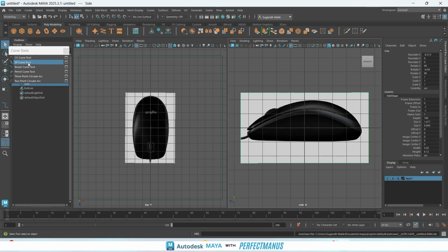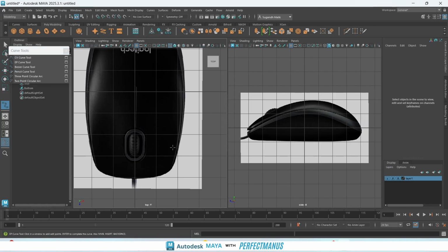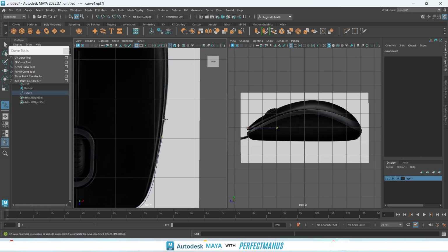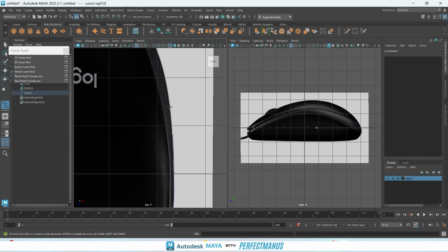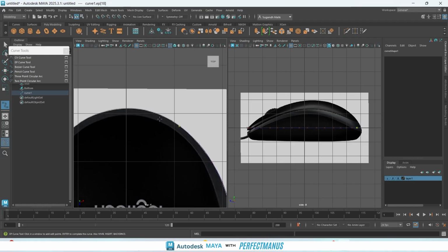We are choosing an EP curve and from the starting, okay, from this area you can start molding, or from this area you can start molding. So I will focus more on the top view because I need to follow these curves and I need those many points. Instead of creating them later on, we'll be focusing on creating those right now, okay. You can see that they are going out, but it's fine, we'll be fixing them. So just simply follow the outer edges, okay. But we could have worked in this one and this one also by moving them up, but it's fine. We'll be working slow and steady and focusing on our result, okay.